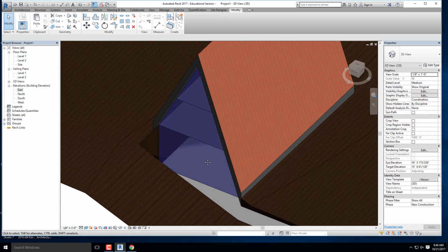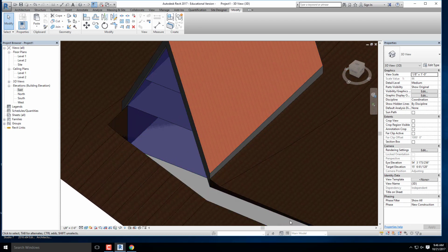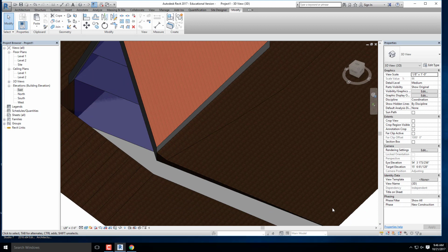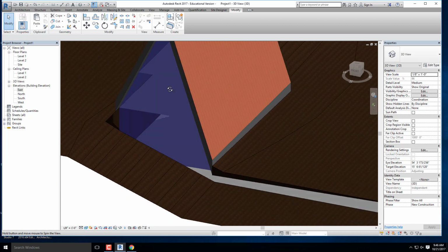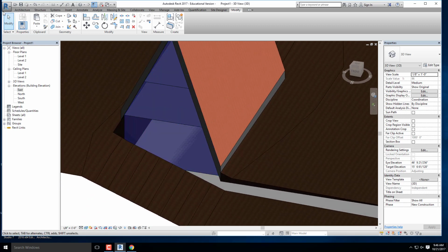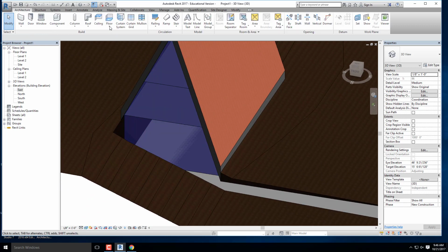All right, I'm not going to add a floor to the bottom because our pad is actually acting as our floor. If you wanted to create a separate floor that is maybe just your finish, maybe you're going to put the hardwood directly over the concrete, that's an option. Okay, but for the upper 2 floors, I am going to do architecture. I'm going to do floor by face.